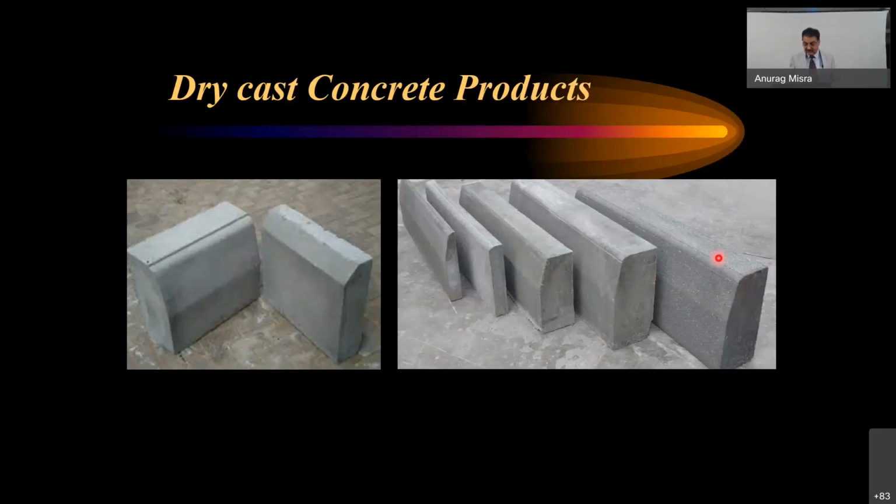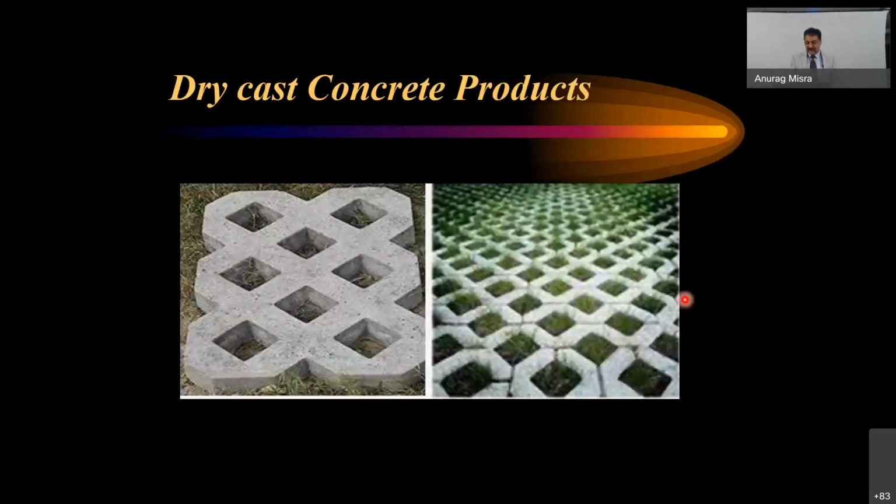These are some of the different shapes, sizes, and thicknesses that could be made for pedestrian use and for national highways. Some decorative ones could also be produced. You have to create a mold for that. These are some of the molds people are using, where you want grass also put in. This is very effective on stabilizing slopes as well. Earlier, if you remember, pitching used to be one of the methodologies for this. Now, this beautiful landscaping could be done on slopes with these precast blocks.